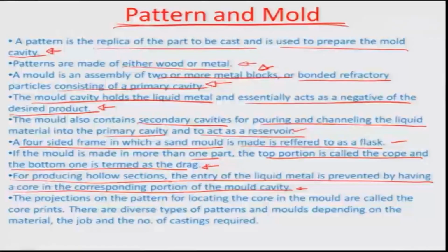So, you can exactly make the design in a manner so that the core can be extracted later on. Okay. So, that is how you do this kind of hollow castings. Okay. So, core is very important. The projection of the pattern for locating the core in the mold are called core prints, as I have just mentioned. It is like legs which are holding the core in place.